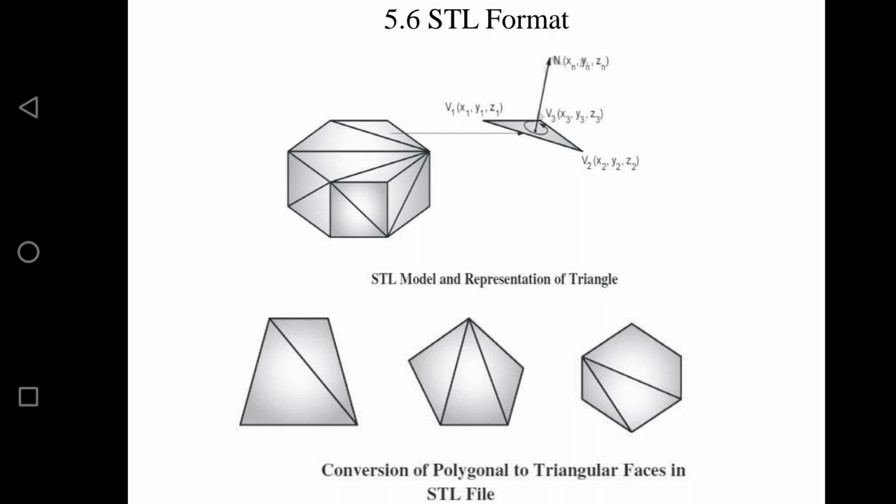What are the disadvantages? If you see, many times the STL file is actually larger than the original CAD data file, especially for complicated shaped objects. We are going to have larger file sizes than the original CAD data. That is one of the disadvantages of the STL file format. And I said while doing rapid prototyping, we are going to do the slicing of the STL files. Okay, this slicing of STL files can take several hours. Okay, it is going to take more time to slice the STL files. So that is one of the disadvantages. And also we are going to face a number of flaws in STL files.